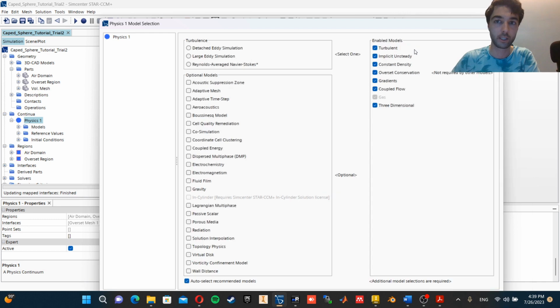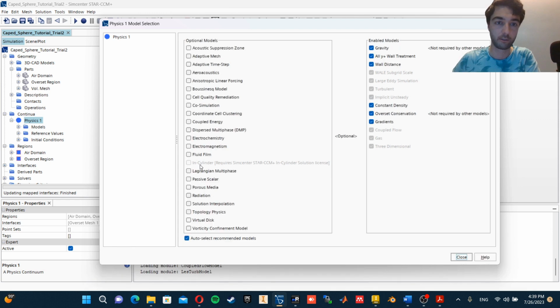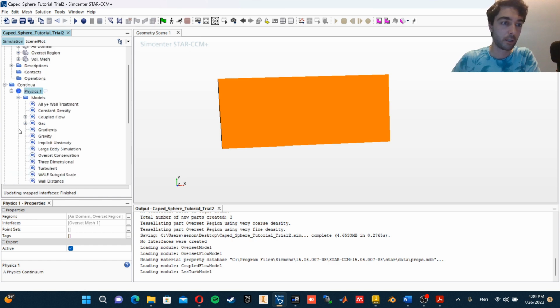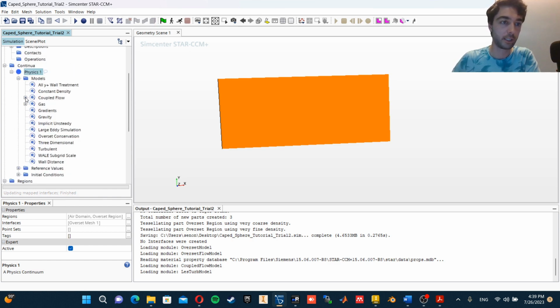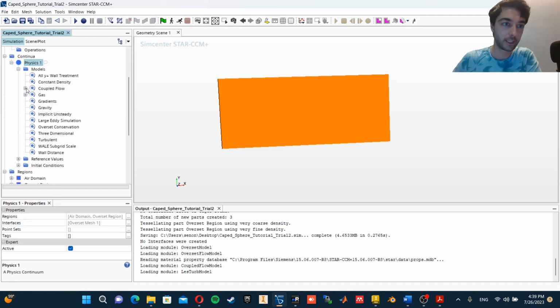We don't want that. We would like to select Large Eddy Simulation, okay? And we would like to select gravity for DFBI. So it's gravity and nothing else. That's all the models we will need. There are a few things we can change here in the physics.